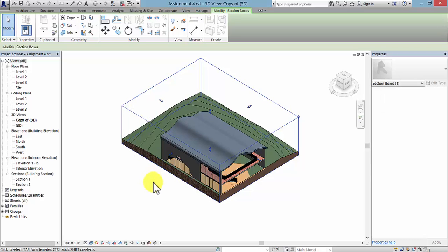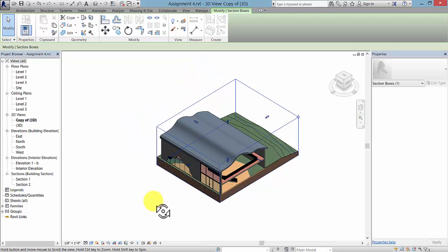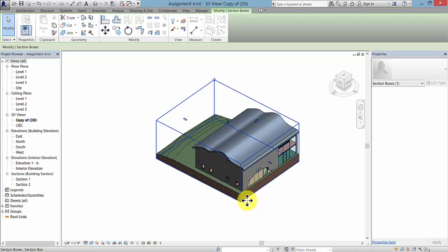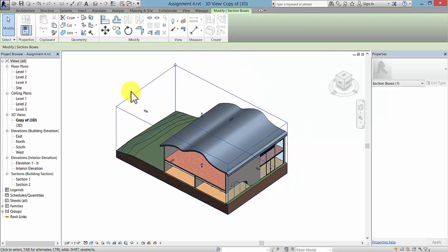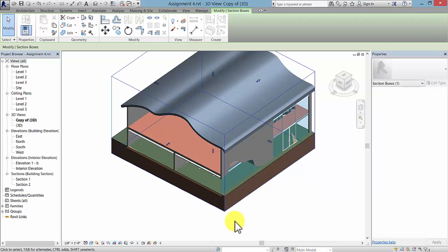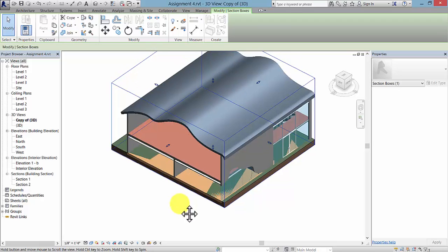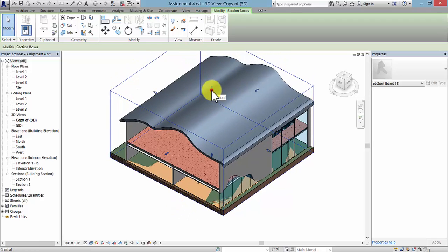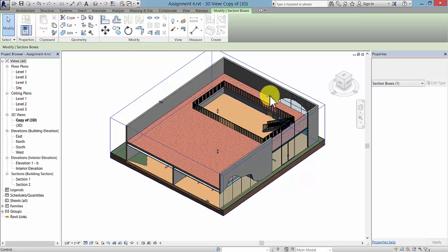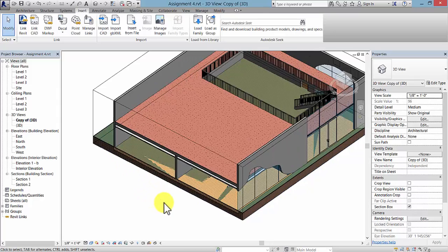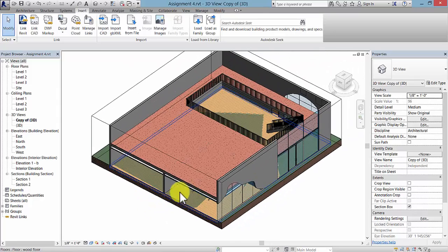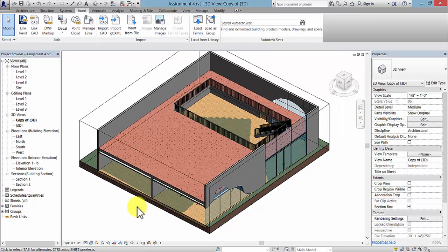with the desired look that we'd like for our graphics. So what I'm thinking is that I'm going to hold my shift key down and press the wheel of my mouse to orbit over to the other side, and maybe create here a section that is only showing visually a piece of this building, maybe not even the roof. We're going to need to create a building pad, because we have a floor, but that floor is kind of in the dirt there. So you can see the variation in the flooring material.